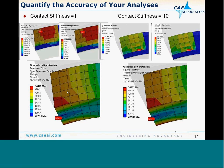The area, or the real area of interest or concern, is the stresses in our individual parts. So if we look at our internal ring and compare stresses between the contact stiffness factor of 1 and the contact stiffness factor of 10, we see that the stress does not change. Which indicates that from a calculation perspective, in terms of error introduced, using a contact stiffness factor of 1 provides a very reasonable result.